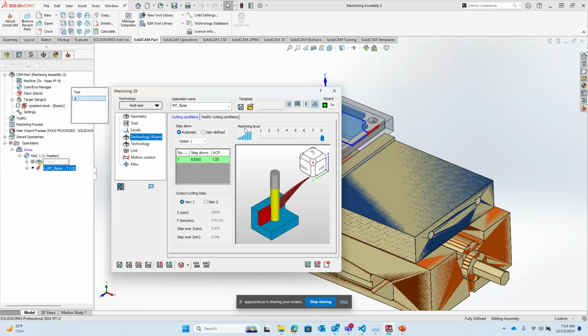So right now, I have this turned all the way up to an 8. So 8 is the most aggressive that iMachining will go. Now, I say aggressive, and I say that iMachining will run very fast, but really, iMachining is only looking to maximize your machine at about 17% of its capabilities. So it is designed very safe.